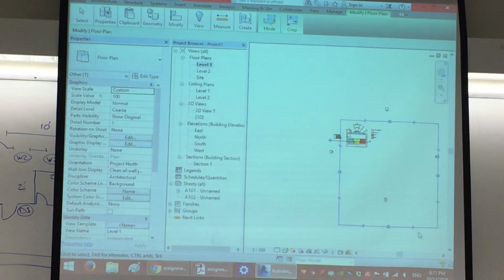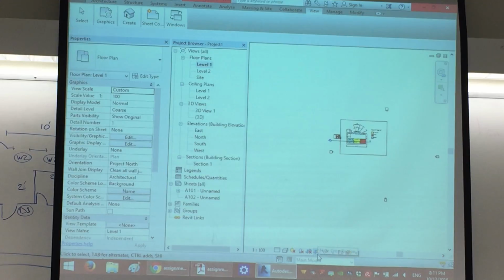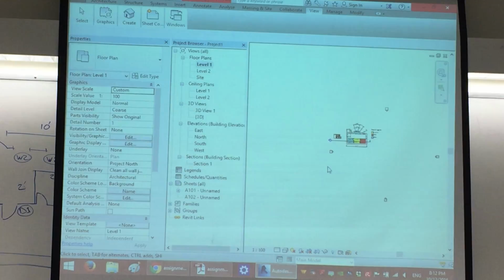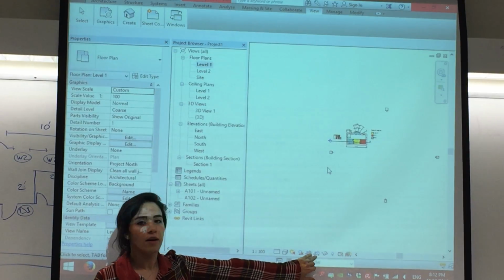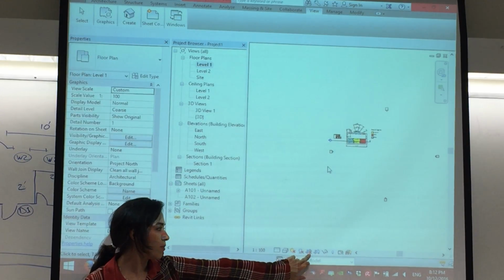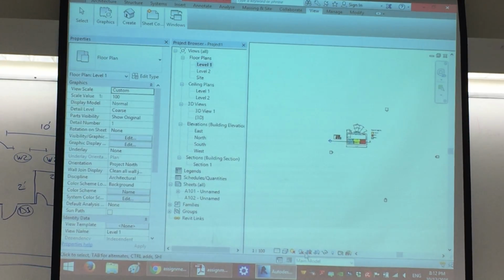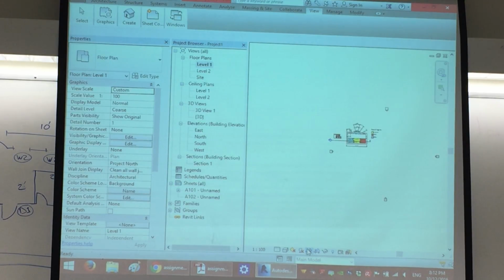You click on that, you drag it inside because you don't want those showing, and then the option next to it, you hide it. After you switch off this, then the option next to it, the view region, you close that as well. You don't get these points in your presentation sheets.